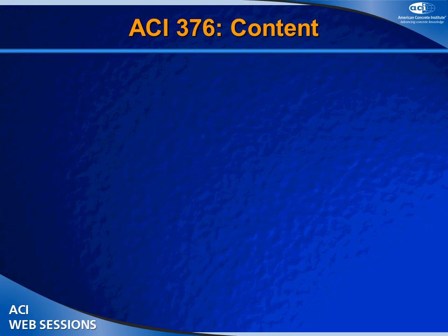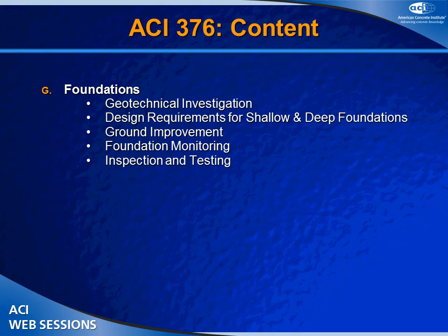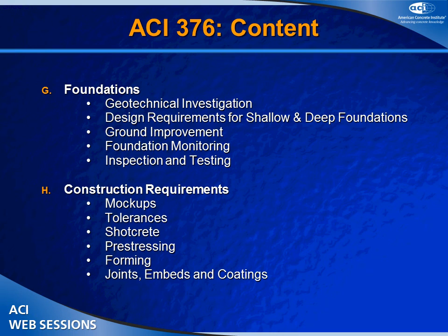We cover foundations. You can imagine, at minus 260 F, there can be some things going on with the geotech. So foundations were important to us. And we're not saying we're geotechnical engineers, but we do give some general guidance on what's required for developing a design of an LNG tank, considering the foundation. Construction requirements: this isn't a spec. It's not like you will see necessarily in a 301 that you can just hand to a contractor, but it's guidance to the contractor. And we're talking about things like tolerances, shotcrete. Shotcrete's not addressed in 318, but we do cover it. Pre-stressing, forming, joints.